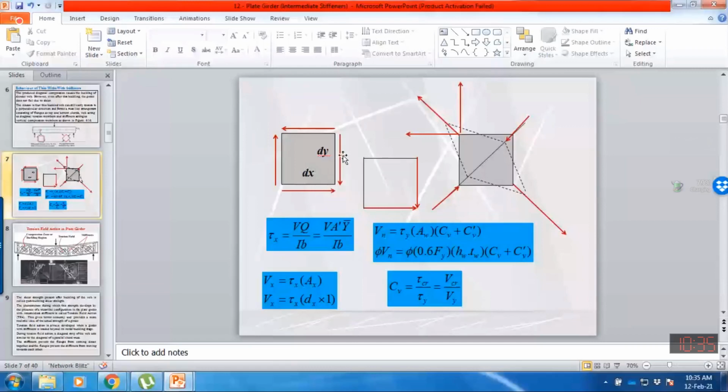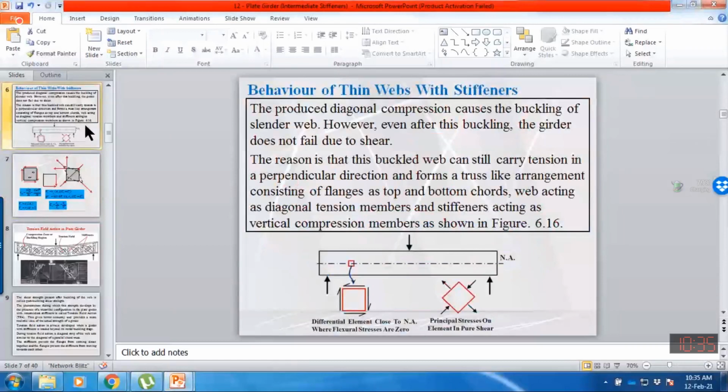So you can discuss these vectors in terms of forces or in terms of stresses. If this arrow is acting in this direction, this arrow is also acting toward this corner. Either their tails meet at the corner, or their heads meet at this corner. So it means that the center point of the web is subjected to these four forces, along the neutral axis, you can say. So the behavior of the forces will be like this.